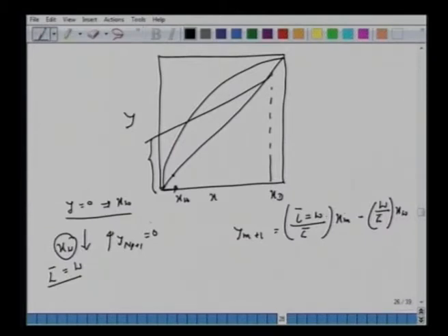So now with this intercept, the negative intercept, you have to connect like this. This will now correspond to your xf or the q line. So notice the difference here. Instead of connecting from here, now you have connected with this x-axis where y equals 0, because this is what the operating line connects. The two phases: the vapor which arrives here, and the liquid which leaves here. The operating line connects like this.